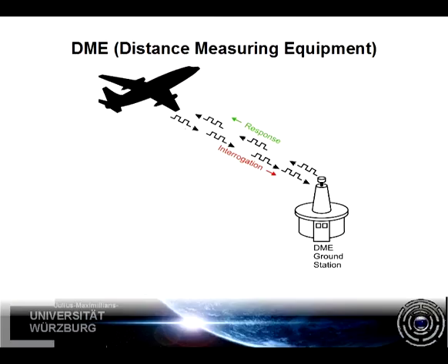Since the DME is usually used together with a VOR, the DME is not tuned separately. The pilot sets the VHF frequency of the VOR station by referencing the chart. The UHF frequency of the corresponding DME is set automatically, since they are always installed with the same defined offset. Interestingly, when there is no actual VOR at a working DME ground station, to be able to receive the DME anyway, the pilot has to set a VOR frequency of a phantom station, so that the DME receiver tunes to the corresponding frequency of the existing DME station automatically.